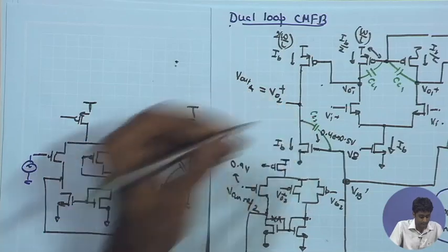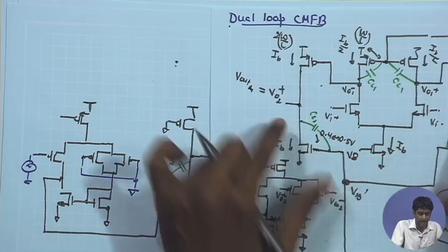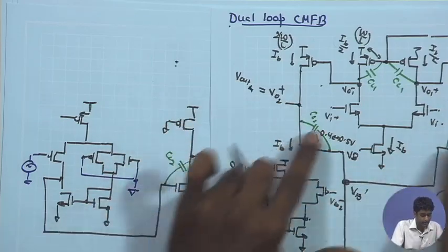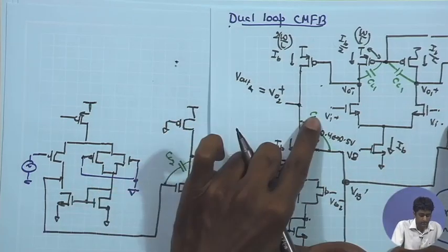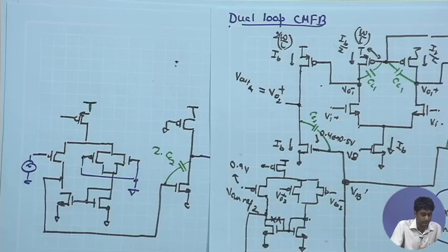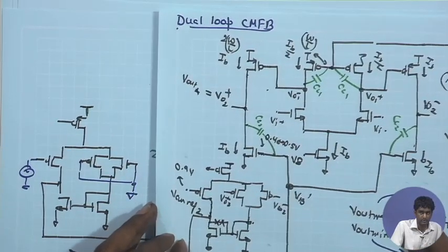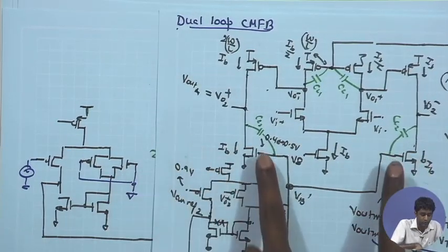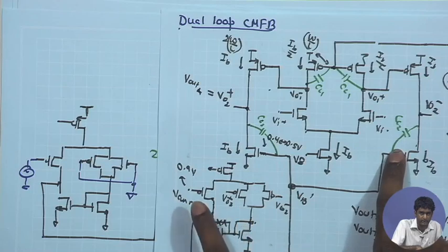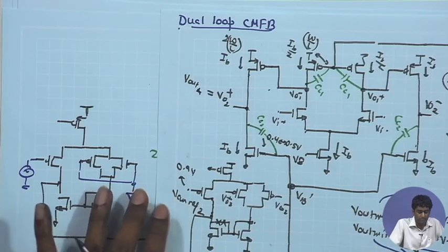And just to be accurate, if I am combining these two capacitors in parallel for the common mode half circuit, CC2 over here will combine to give you 2 CC2. So, actually this should be 2 CC2, that is just to keep the numbers correct. But structurally this is how it is going to appear in the differential circuit. It is going to appear between the output of the error amplifier of the second stage CMFB and the output of the second stage in our overall amplifier.